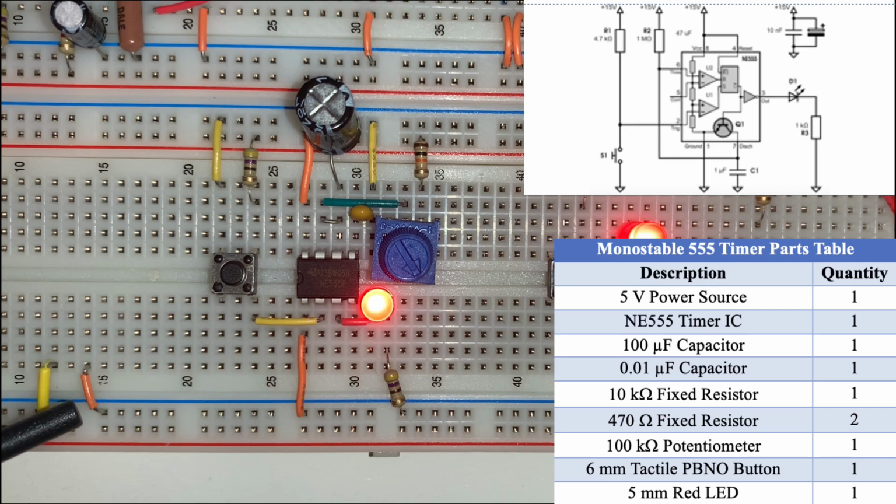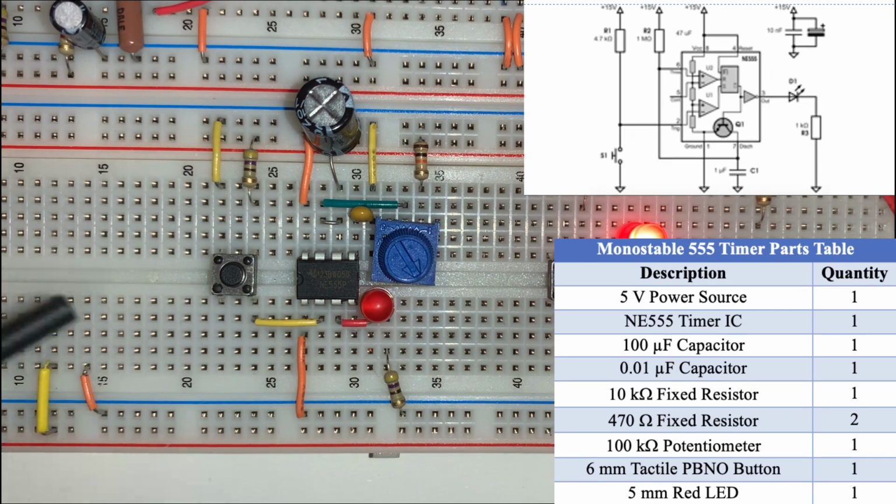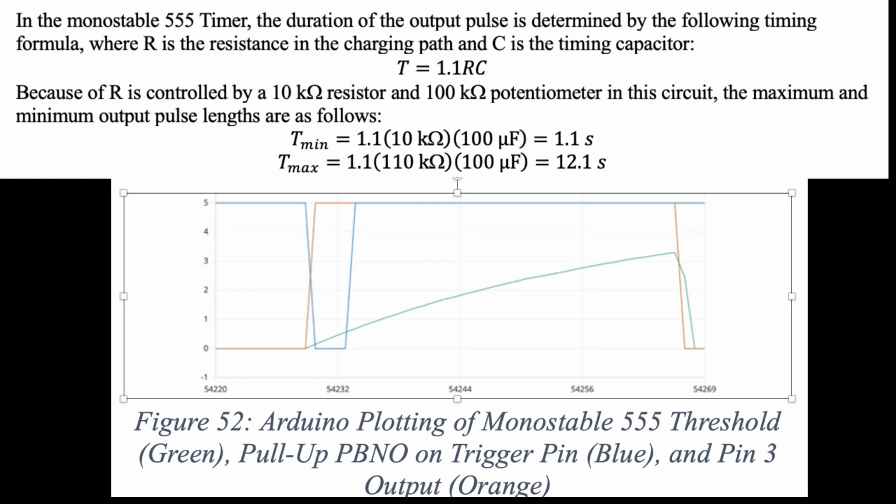The LED turns off, the discharge transistor discharges C1, and the circuit returns to a stable state until triggered again. The pulse duration depends on the RC time constant on screen. For the chosen components, the minimum and maximum pulse durations are 1.1 seconds and 12.1 seconds, verified using the serial plotter.